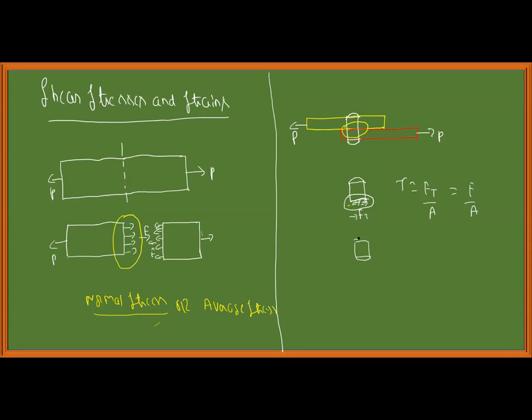If I write the stresses like this, and if I take the resultant Ft, the same thing holds good. You can see the difference here. This was perpendicular to the cross section. This was a cross section, and the stresses were perpendicular to the cross section. Whereas here, stresses are parallel to the cross section. This tangential force per unit area of cross section is called a shear stress. Its unit is also Newton per mm square, or MPa, or Newton per meter square.